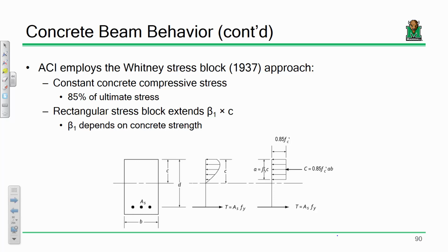Okay? The idea is that instead of this, remember, this is f'c. So remember, to create an equivalent box, we say that this is 0.85 f'c. So the box has a width of 0.85 f'c. It has a depth of a. And so you're going to see some terms here that are a little unfamiliar, like this term beta 1 and whatnot. It doesn't matter. Don't worry. We're going to delve into each of those terms in the next couple weeks. You really don't need to know about that right now.